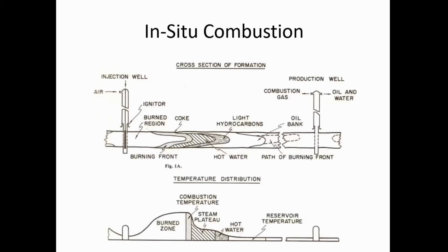In-situ combustion: I have seen that in certain countries, they use the injection well as a burning well. They set a fire on the injection well and connect it to an air compressor. We have an igniter, and we have oil, and we ignite the oil inside. So we have very hot burning oil inside the wellbore, pushing it to the producing well.